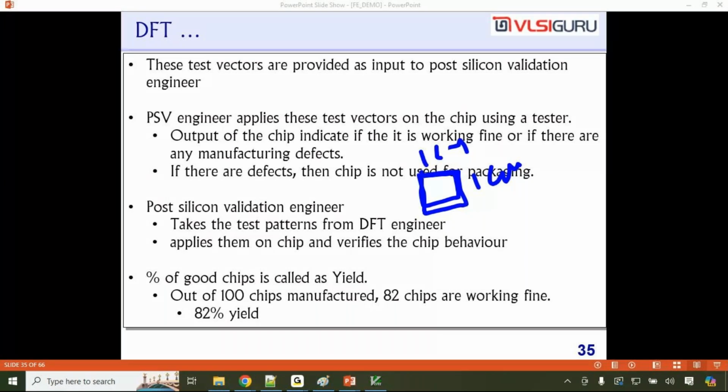You understood, right? Basically, to verify a chip for manufacturing defects, you need to modify the logic a little bit. You need to add some circuitry called built-in self-test. Also, you have to change the normal flip-flops to scan flip-flops. There are some changes that need to be done. Some of those changes are done at the RTL level, some of them are done at the gate level. So hence work happens at both the stages.